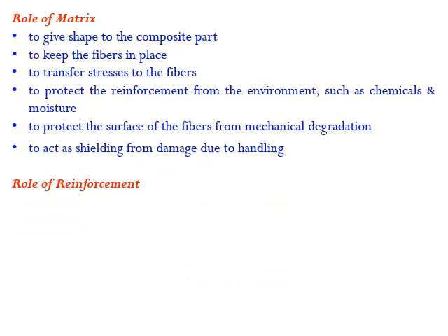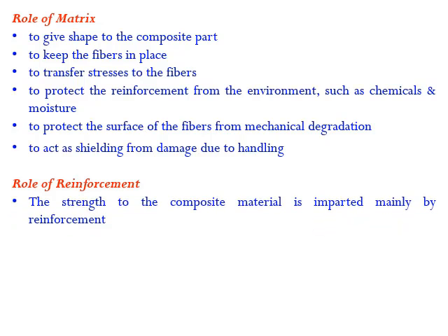So whenever we are going to handle the composite material, we are playing with the matrix material, that is the outside material. Even when it comes to the reinforcement, the reinforcement is within the matrix. The matrix is the one which comes in contact with the environment.